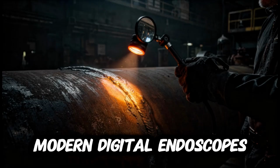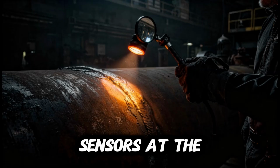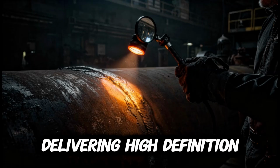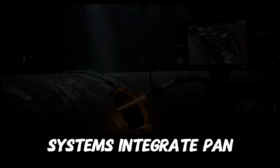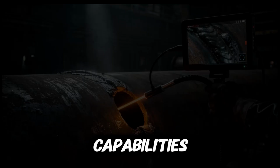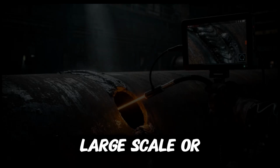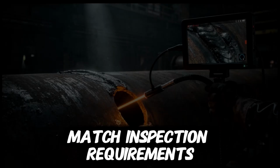Modern digital endoscopes replace fiber bundles with miniature CMOS sensors at the distal tip, delivering high-definition imaging, adjustable LED illumination, and onboard measurement software. Closed-circuit television systems integrate pan-tilt zoom cameras with remote monitoring capabilities, primarily used for large-scale or hazardous inspections. Light sources must match inspection requirements.